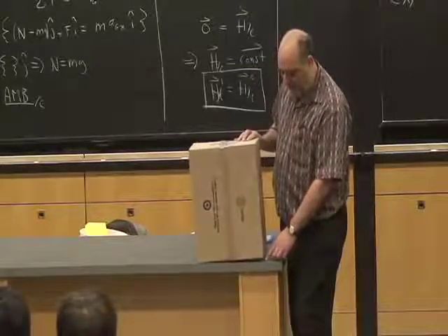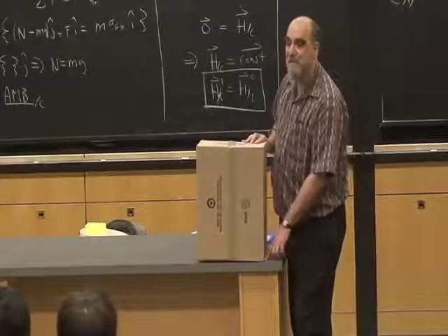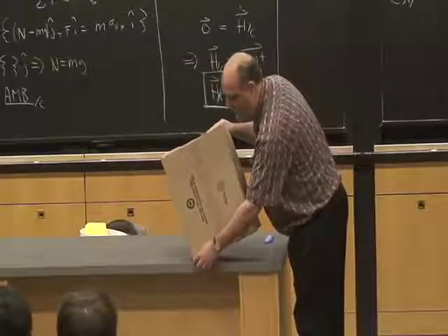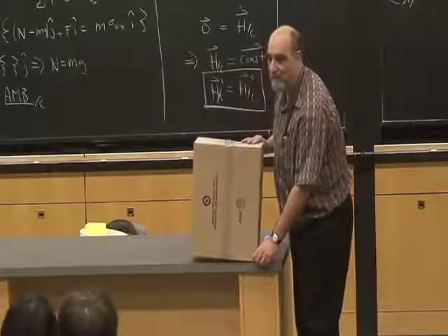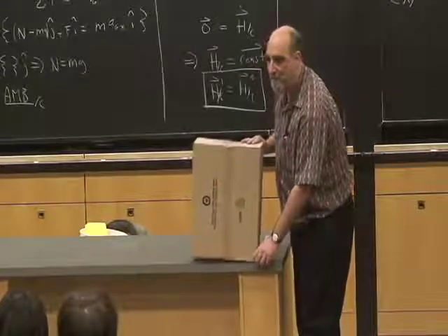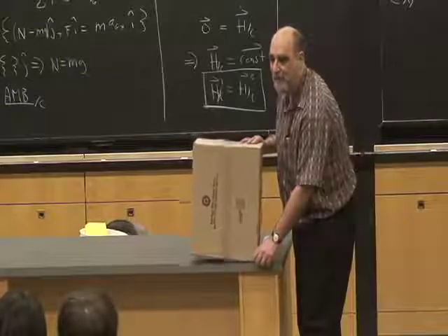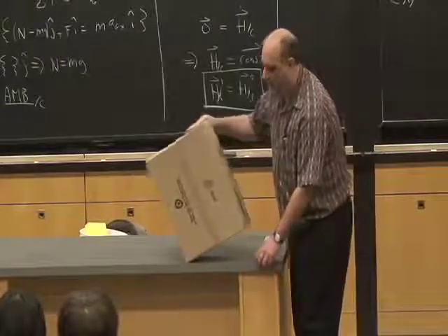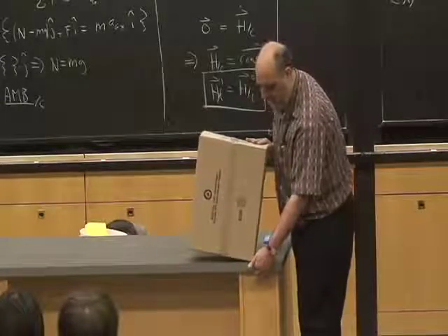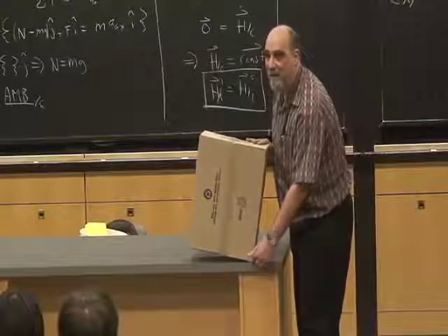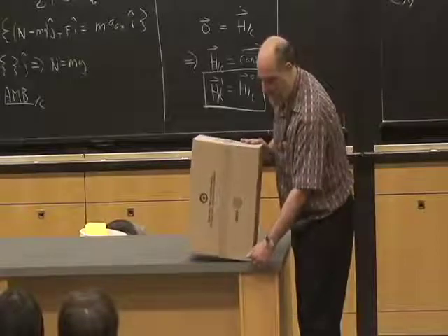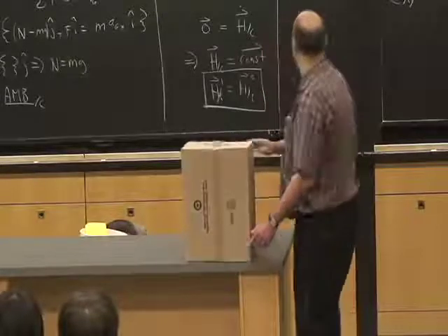So what happens is between this state and the next state there's some jump in the velocity and angular velocities, which is consistent with this changing from hinged about this point to hinged about this point. And we have to look at balance of momentum, angular momentum in that process, and then we'll conserve energy again while this rides up to here. So if we want to figure out how high this lifts up, we have conservation of energy. We have this collision to analyze, which we're going to analyze by doing conservation of angular momentum, or angular momentum balance, about this point, where in this case we're actually going to use angular momentum and not its rate of change. And then we have conservation of energy back up again.